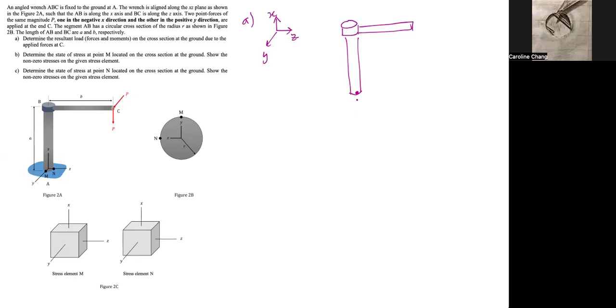So at the origin, there will be reaction forces in the positive x direction, in the z direction, and in the y direction. And notice that although this is kind of like the negative z direction according to our coordinate system for the external forces, it's actually positive when we are considering the internal reactions because these are the directions that define this beam in tension.